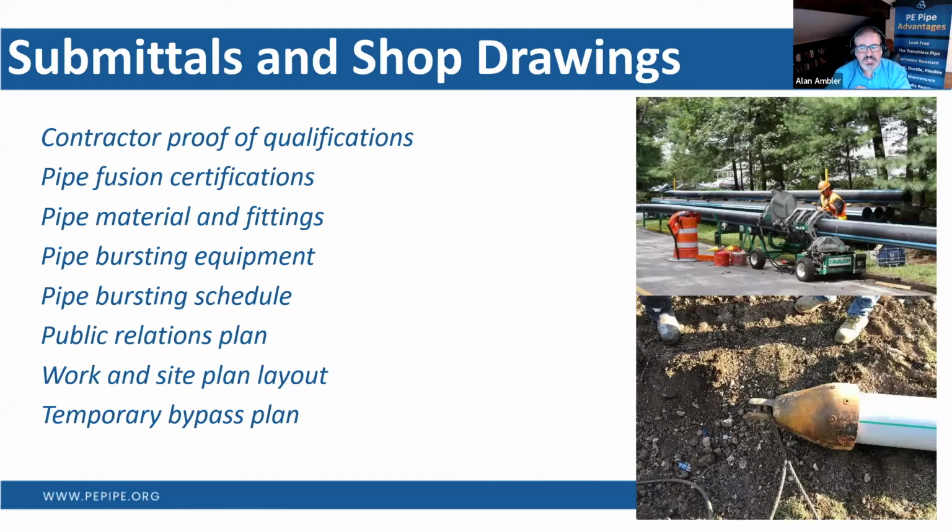So when we're trying to keep that flow invert exactly aligned for gravity flow into the manhole, and making sure that everything downstream or upstream is not impacted by lowering that flow line, in gravity sewer, it's up and out. So yes, you can assume that the invert elevation still stays the same. Thank you very much for the opportunity to clarify in that manner.